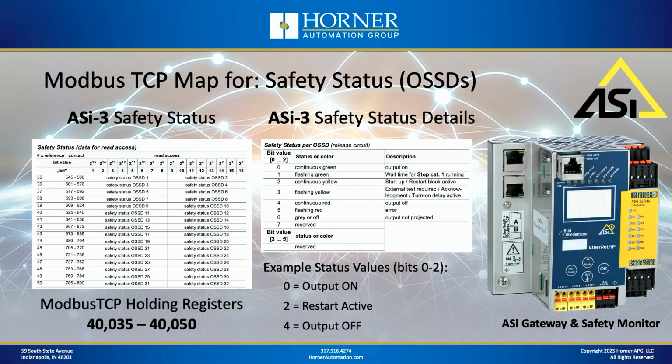Now, in addition to the standard ASi input and output data, there's also the status for the safety outputs, the OSSDs. And those are available in a different location, a different holding register. There's a bank of, I believe it's 16 holding registers. But if you only have a few safety outputs to manage, then you're just going to be looking at a couple, maybe a few more than that, holding registers to get the status of your OSSDs.